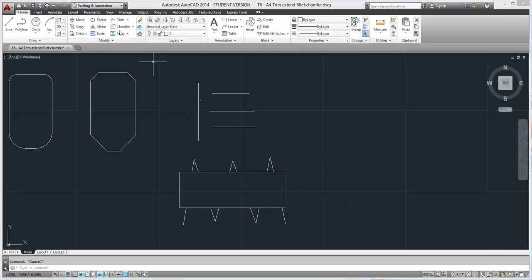Okay, so now within the trim command, if you do the drop down button, you have something called the extend command. If it will drop down for me, there we go. It's right here. So by clicking the extend command, all of these lines to my drawing right here, let's say that I wanted them to actually extend to this line. I didn't make it quite long enough. I guess I messed up, whatever the case is. I can use this command to fix that problem.